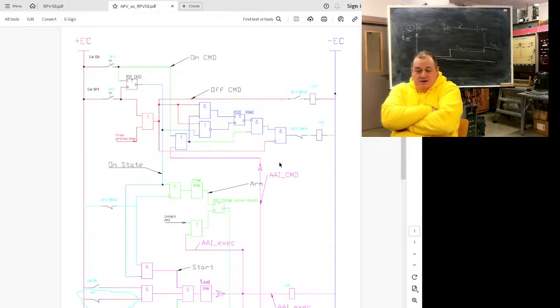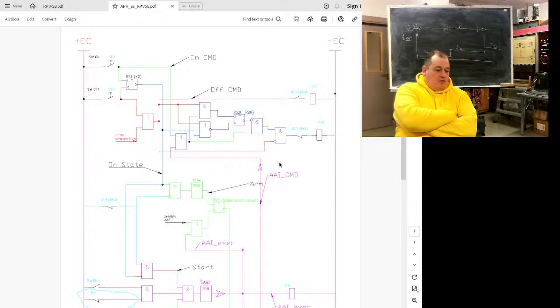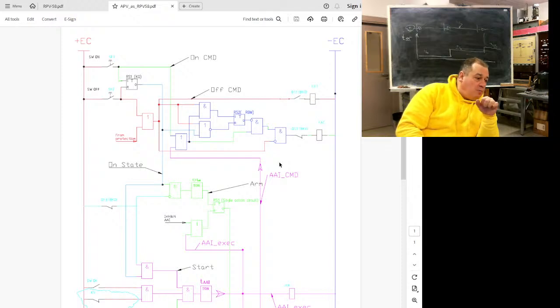Really good stable logic, but it's usable only for radial lines. The problem is if we have power sources from both sides. The problem is in non-synchronous reclosing.